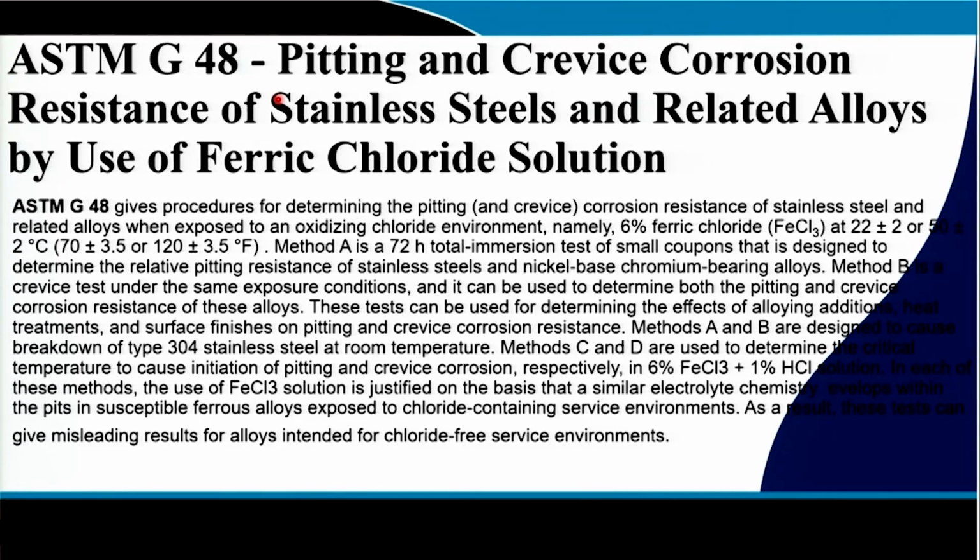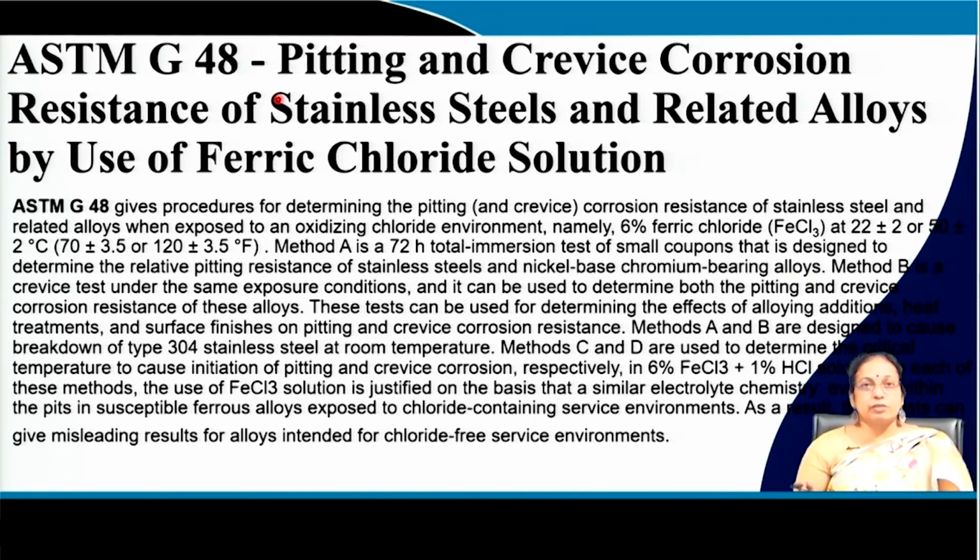So, if you measure either electrochemically or chemically the weight loss because of pitting corrosion, it will misguide you. It won't give the exact aggressiveness of that particular situation, or how aggressive the solution is to cause the corrosion. So, what is mandatory there?